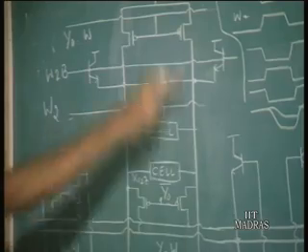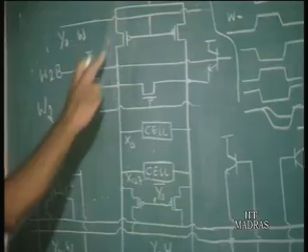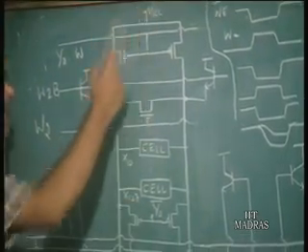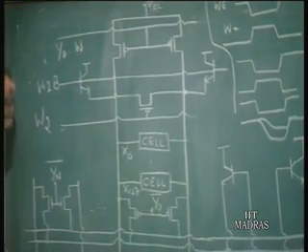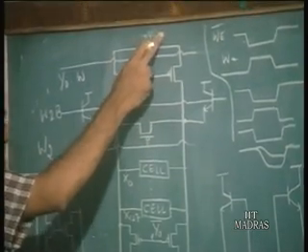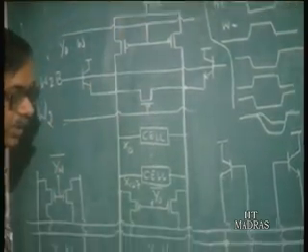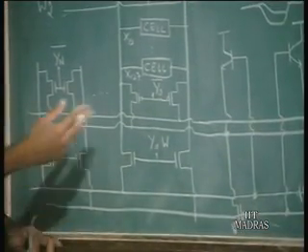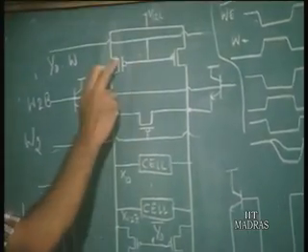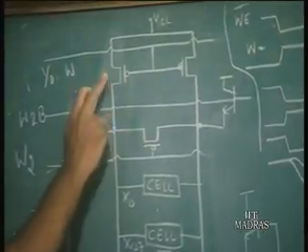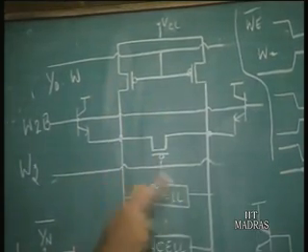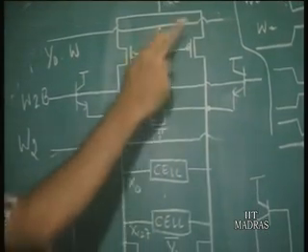So this is the circuit of one column. This is how one column is going to look. Again, internally, as we said, it is BiCMOS levels, so these are negative voltages as in a BiCMOS memory. VCC would actually be ground and the other supply would be negative. Now, for the reading operation, while you are reading a particular cell, these PMOS transistors here are on, and these transistors form the load for these cells. This forms a low resistance load for these cells.